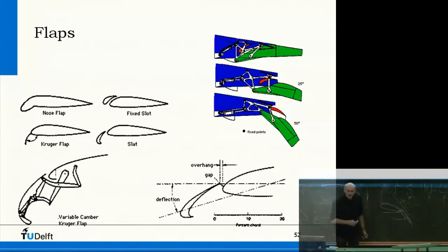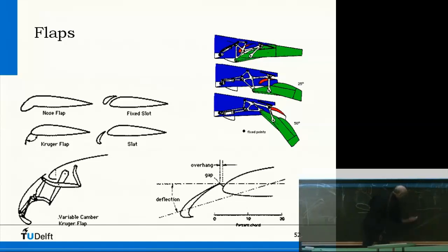It's the same as when you look at ailerons, for instance. If you have a wing like this, and you have ailerons here, then sometimes you see on a wing these small things of this type or of this type. These are called vortex generators. Would the flow separate in front of this aileron, then it's not effective anymore.